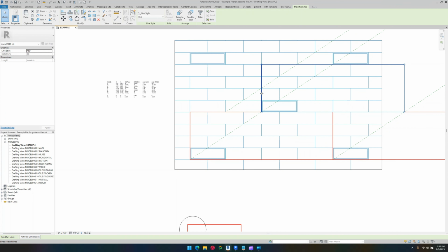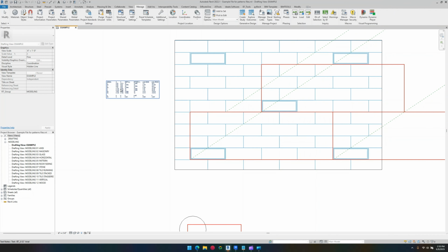Otherwise, if we didn't do this sort of orientation, we would then have a bigger box that would be something along the lines of this, where we need to have a pattern here and a pattern here. And we don't want to do that because that then creates extra line work. It creates extra rows. Revit has to calculate and render all that out. And so it just makes things a lot simpler.